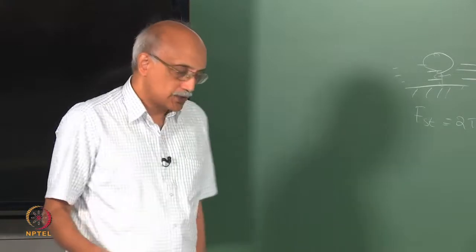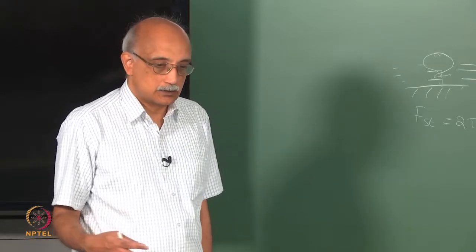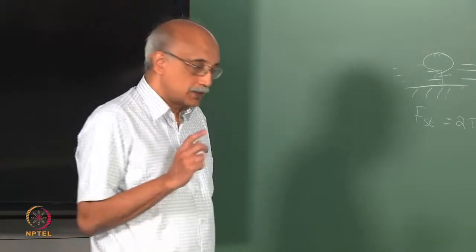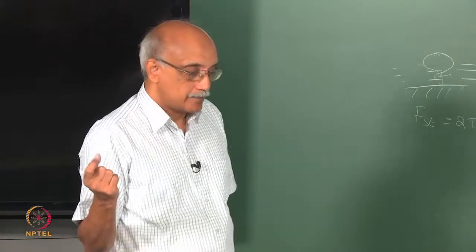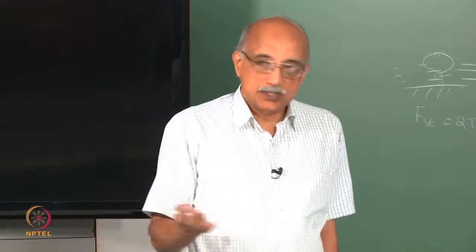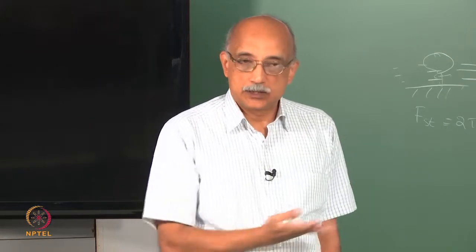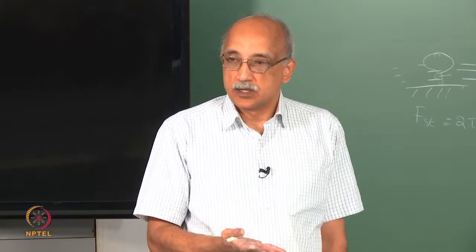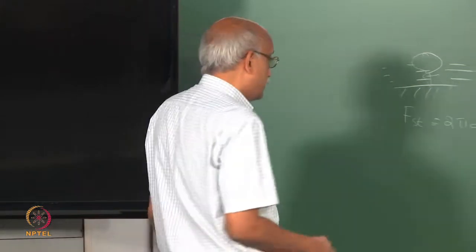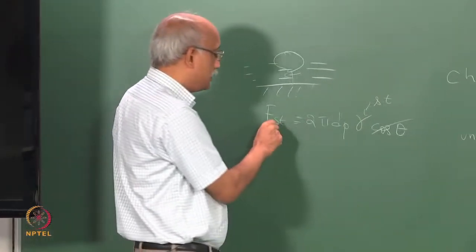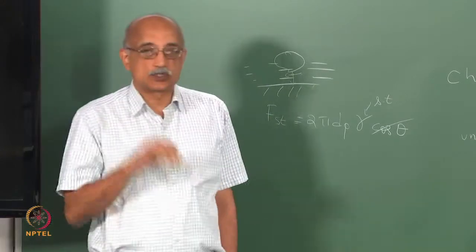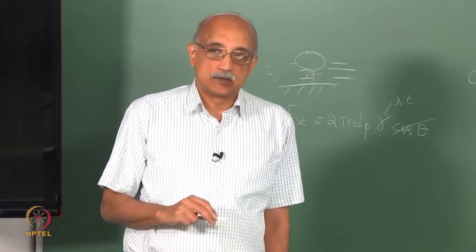So, I mean surface tension based forces are fairly simple to envision, but there is a little bit of a trick here in that by reducing surface tension you make it easier for the liquid to wet the interface between the particle and the surface. But at the same time when you reduce surface tension you can see that this surface tension force also decreases, right.